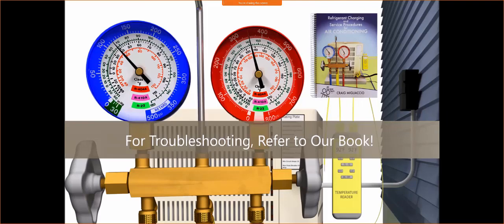Big disclaimer, if you have an ice ball, anything like that on an evaporator, condenser, lines, all that stuff, don't hit it with the hammer, don't hit it with the screwdriver, don't do any of that stuff. You want to let it melt. If you want to apply a little bit of heat to it, you can via heat gun, pouring warm water on it. You can have the furnace blow air across it to help just naturally melt. Whatever it takes, but by no means use any type of physical force to try to do that, because you may rupture one of the lines. If you rupture one of the lines, you're going to have issues. So keep that in mind.